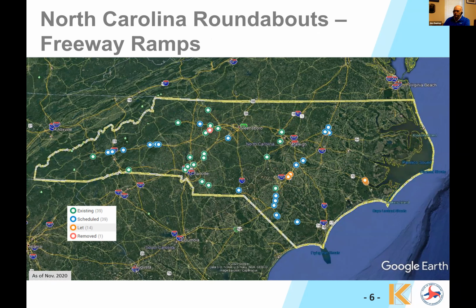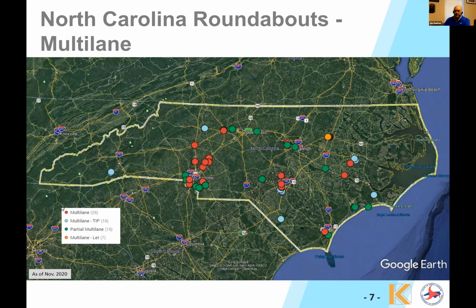If you're working on a new or renovated interchange with relatively low volume, roundabouts at the ramp intersection should be your default. This improves safety, especially concerning wrong-way drivers, and should last for decades without changes. Now, finally, to the primary subject of this presentation on the next slide, multi-lane roundabouts.